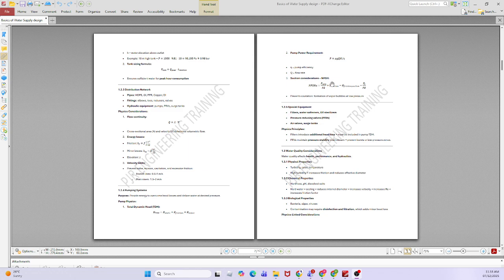Here there is NPSH, net positive suction head. Why do we calculate NPSH? To avoid any cavitation. If there is any cavitation, it will affect, for example, the blades of the centrifugal fan, or your components, or the internals of the centrifugal pump. Cavitation is like bubbles, air bubbles. They may hit and damage your equipment. That is why we calculate the NPSH as well.